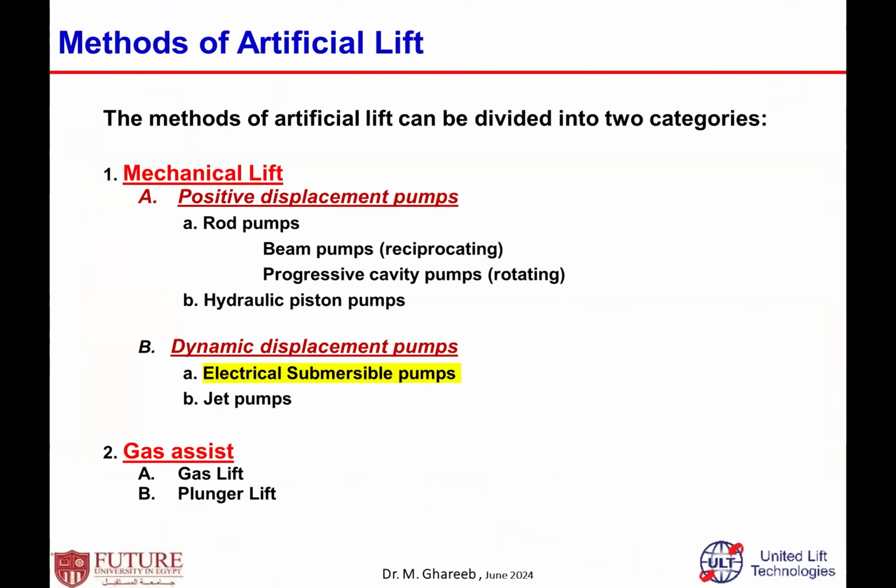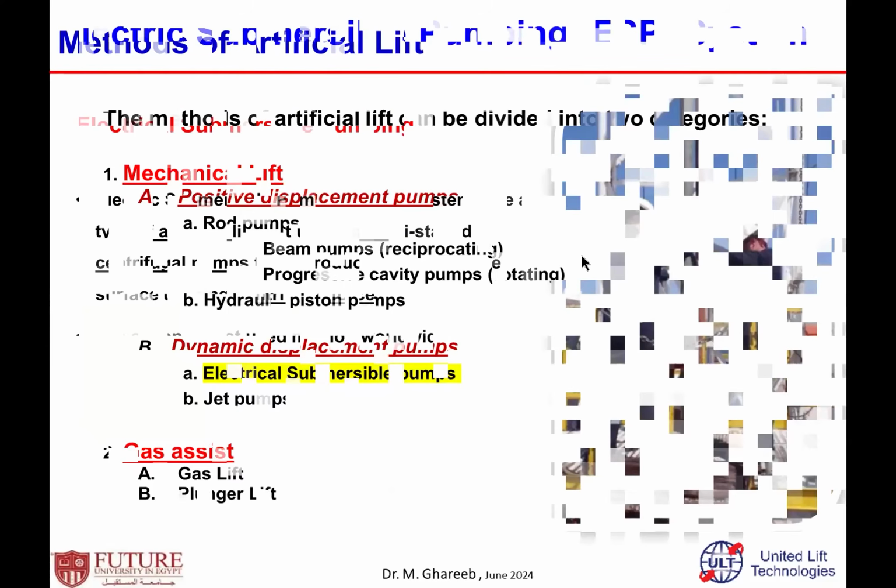Also, when we divide artificial lift, we divide it into two, as I said, mechanical and gas or formation assist. Even within the mechanical ones, we have positive displacement and dynamic displacement. The ESP is among the dynamic displacement pump systems. The pump itself is a dynamic displacement pump technique or system and so on.